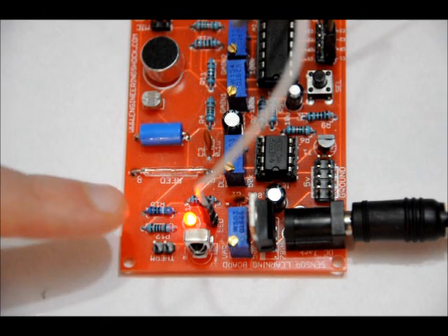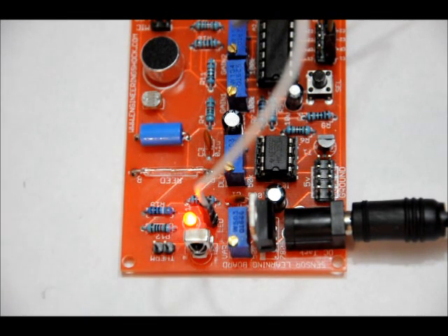Now also what we can do, the output is normally high right now. Remember me talking about inverting the logic? All we have to do is change the inputs to the comparator. So right now we've got the div 1 line from the LDR circuit to the negative input of the comparator, and the 3 volt calibrated voltage from our variable resistor to the positive input of the comparator.